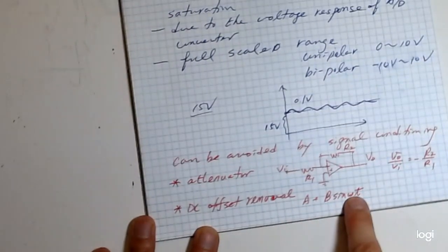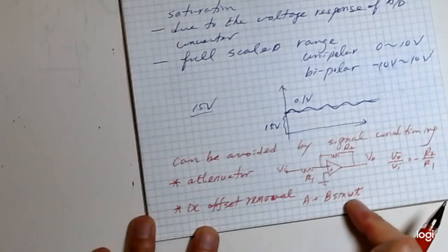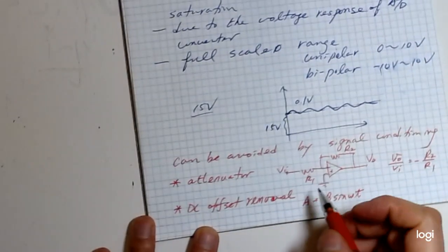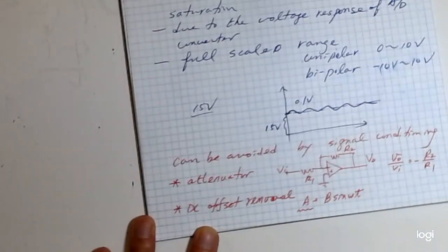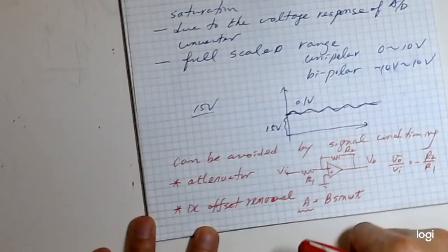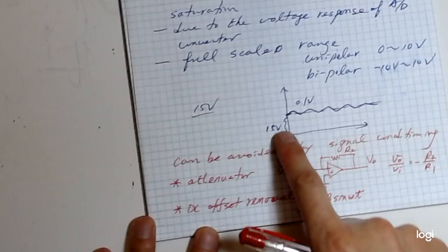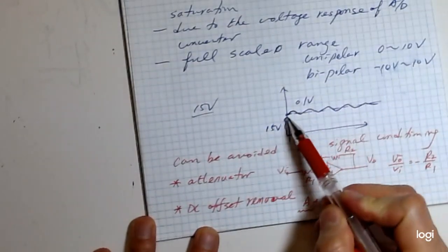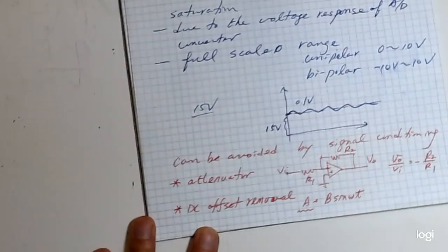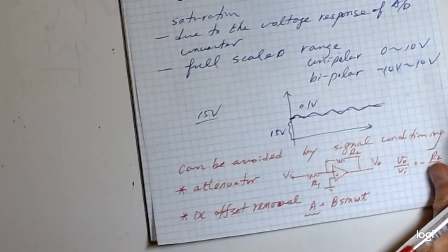Yes, you might change the frequency content, but if you know the frequency, you can get that back. But you can definitely take this constant out. Or you can just offset it with another minus 15 volt. So you only get the dynamic part and remove the constant voltage.